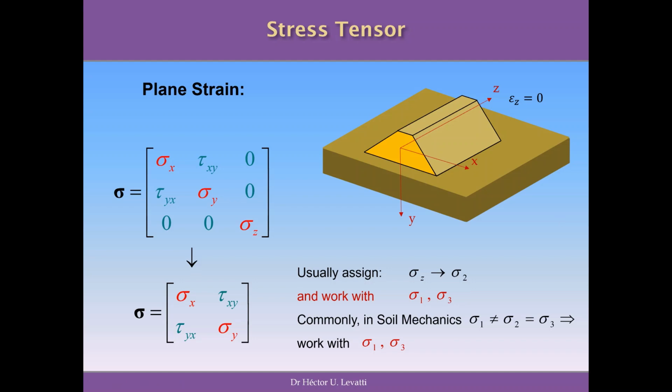Now, there is another concept which is certainly important in mechanics in general, in structural analysis, and in the analysis of geotechnical problems, which is the problem of plane strain. A problem is called a plane strain problem when, for some reason, in the conception of our problem, we can say that one of the strains, for example the strain in the z direction, is equal to 0.